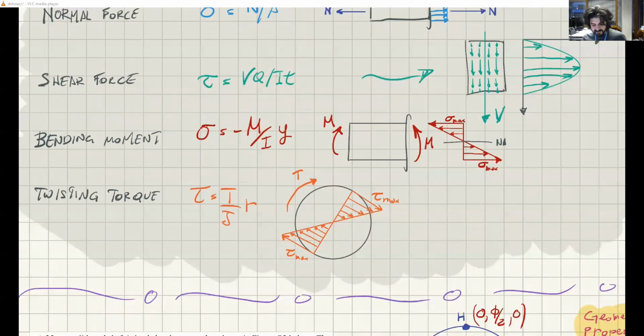This shear stress is distributed in a linear way along the entire section. So if you take any diameter, you can always find the distribution of stress that depends on the distance from the center. This R stands for radius, and it's the distance from the center. You have no stress here at the center, and as you move away from the center, the stress increases. So this torque T comes from the integration of this stress distribution.